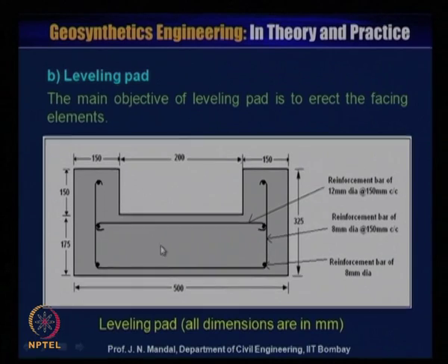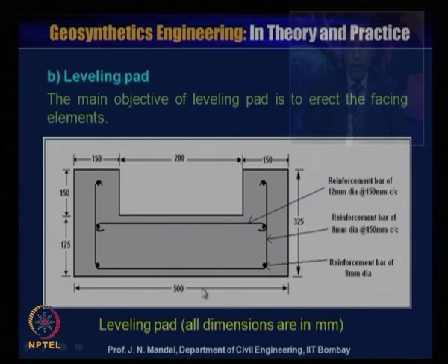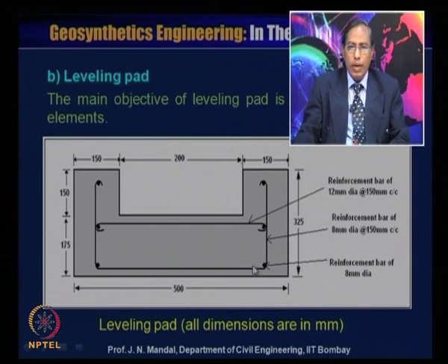So, this is one that shown the leveling pad with dimension, what is the reinforcement bar, 8 millimeter diameter at the rate of 50 millimeter center to center, and here the reinforcement bar at 12 millimeter diameter at the rate of 50 millimeter center to center, and this is 500 millimeter, this is 175, 150 and 150, and this is about 200 and this is 150, and this total is about 325.